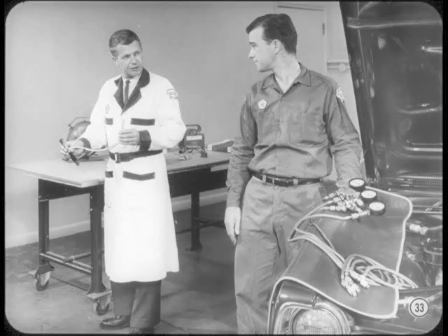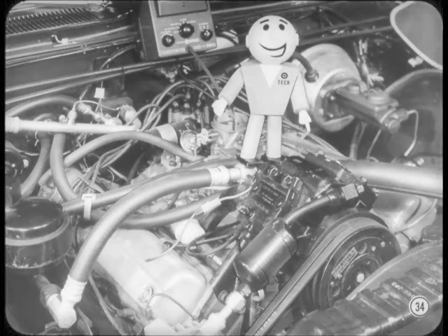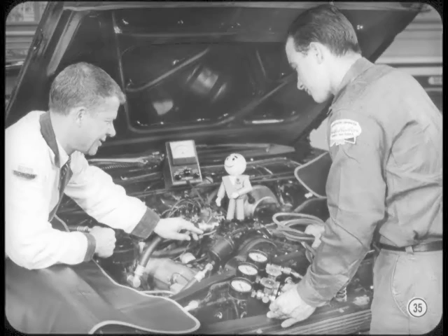The second condition is no cooling at all because the system is empty. This condition usually results from a leak, so you'll have to find the leak first and correct it before any other tests can be made. Compressor crankcase oil can be lost from a leaky system, so be sure to check the oil level before you charge the system after fixing a leak. And don't forget what Fred said earlier about belts, air doors, and the water valve. Check them all. Thank you, Tech.